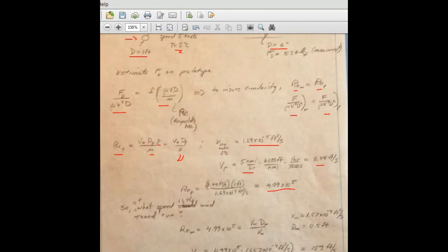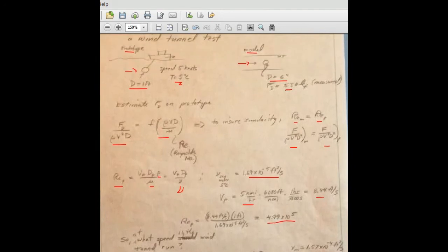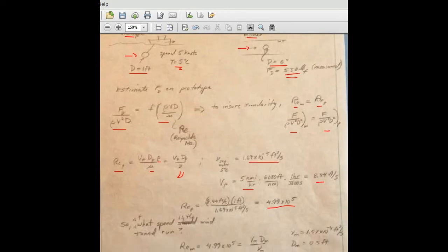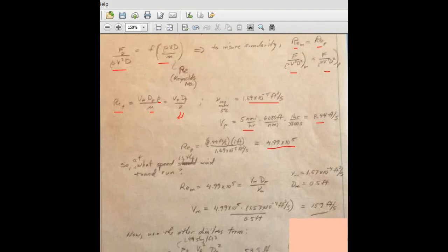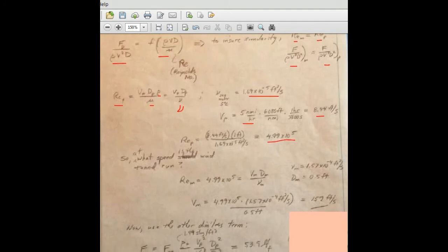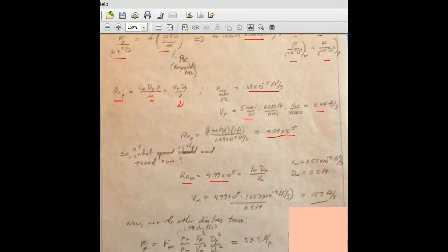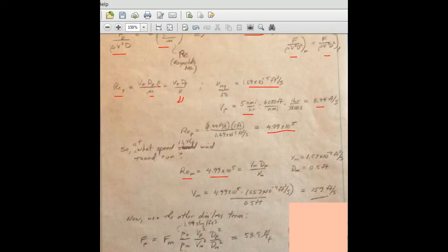So we are given, remember back up here, that the force of drag on the model in the wind tunnel is 5.58. And so that would tell us what speed the wind tunnel is run at. And knowing that we have the same Reynolds number for the wind tunnel, that's what we just assumed when we said that we have a similar system. So that's how this modeling works, and that's really the key to these problems, is you calculate the Reynolds number for one side, but then what for the other side.